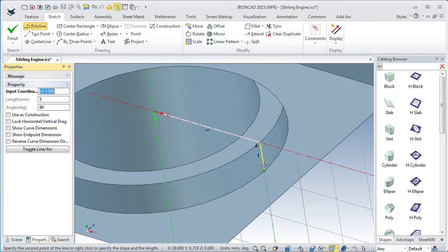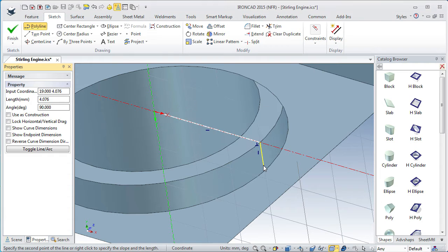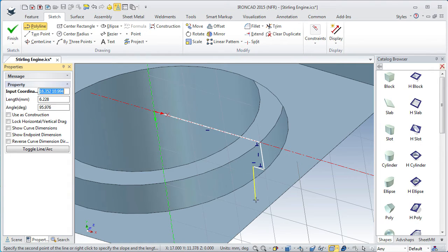And this distance here is 5 mm. And I will right click when I drag perpendicular to the x-axis, right click to type 4.8 millimeters, because it will be a gap between this flange and the cover of 0.2 millimeters. Then I will drag perpendicular to the y-axis. You see the green dotted line, and I will right click. Here I will type 2 and hit enter, like so.